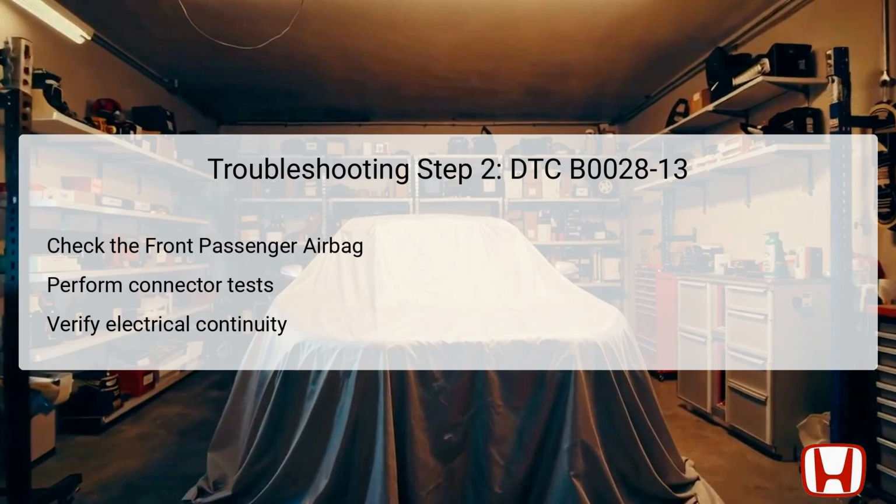For further testing, install a jumper wire between the terminals number 1 and number 2 of the front passenger airbag inflator connector. This critical step allows you to simulate standard operating conditions.